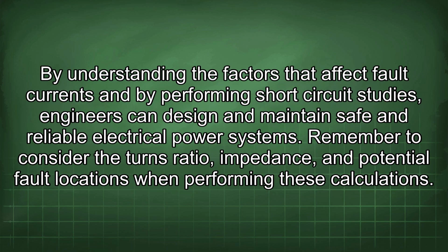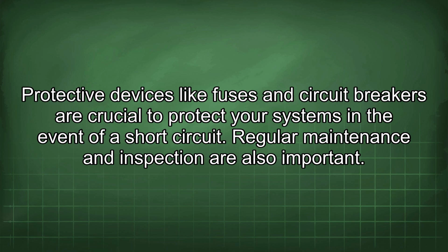By understanding the factors that affect fault currents and by performing short circuit studies, engineers can design and maintain safe and reliable electrical power systems. Remember to consider the turns ratio, impedance, and potential fault locations when performing these calculations. Protective devices like fuses and circuit breakers are crucial to protect your systems in the event of a short circuit. Regular maintenance and inspection are also important,